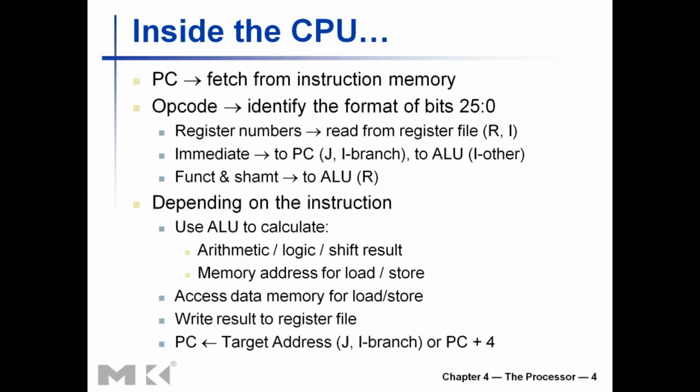the memory address is usually given as two different parts. One is the base register value, the other is an immediate offset value. So those things you need to add together. So in load and store operations, the ALU is used to calculate the address of the memory, whereas in arithmetic or logic type instructions, the ALU is used to do the arithmetic or logic operation on the